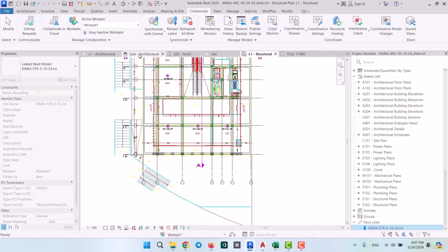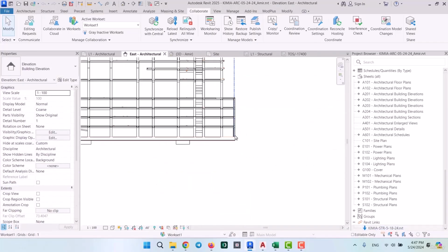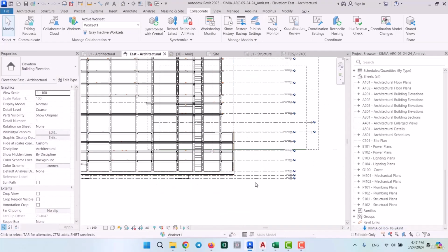Let's go into an elevation, where we can see that those levels that were visible here by mistake are no longer visible. So this way you could also control the visibility of some of your items. And also this is what we usually do for our projects in Revit. We just basically close the grids and levels worksets in the linked file, which also you just saw that the worksets can be separate. Now also you might wonder what you should do if your file isn't central.